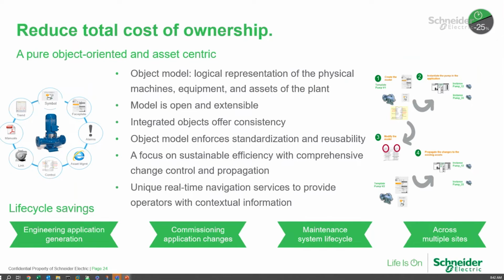It's a very object-oriented system. So an object template to us includes everything having to do with an asset. So not just the logic, but the graphic symbols, the pop-ups, the faceplates, alarm configuration, trend configuration, documentation can be linked to it. Any asset web pages, say you've got a VFD, you can link the web page in through the runtime navigation services. All of that is a core part of that object instance and is configurable in one place.